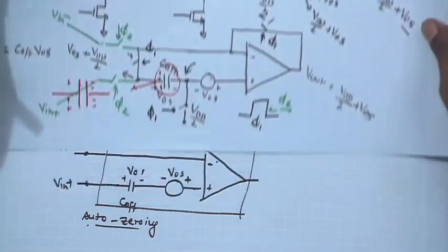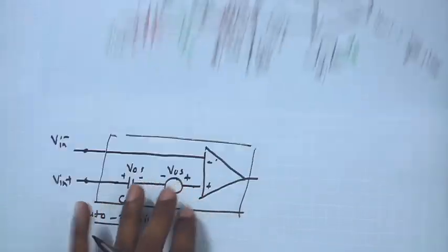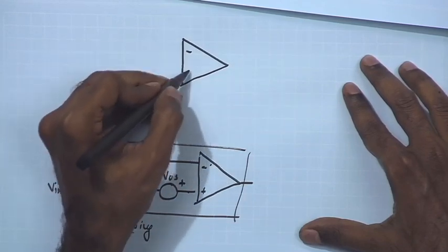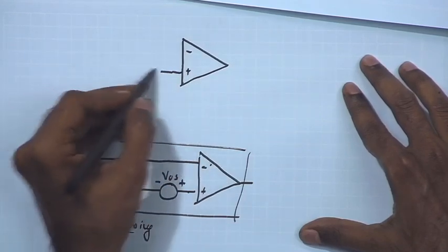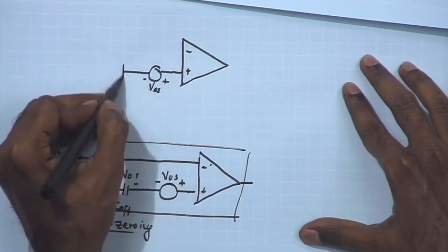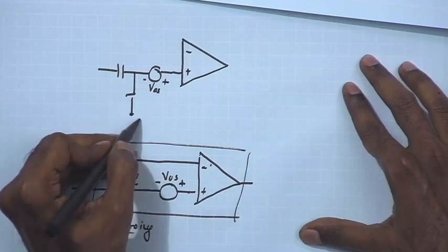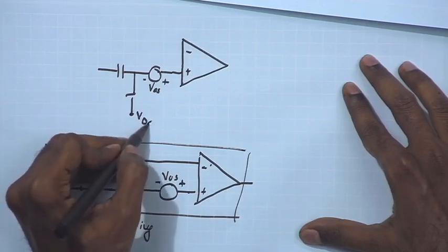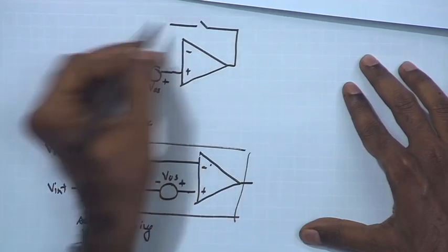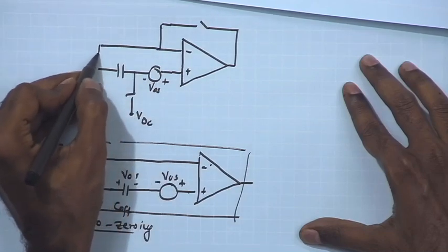So, ultimately we have the overall offset cancellation circuit given by this scheme, where we can call it say any particular VDC, it can be VCM, and then you have switches over here connecting the negative feedback, and then also you have switches over here.